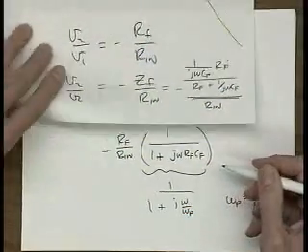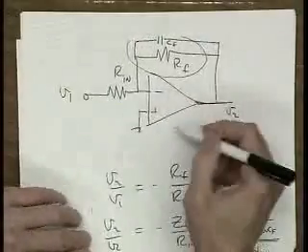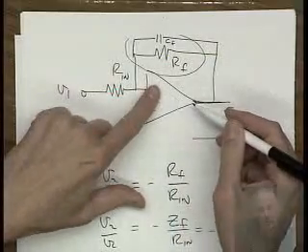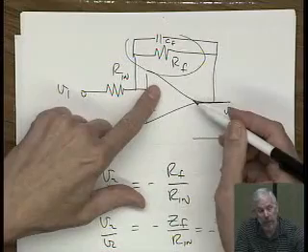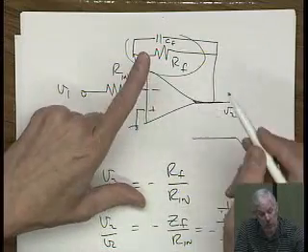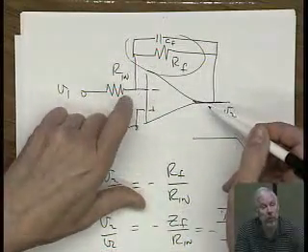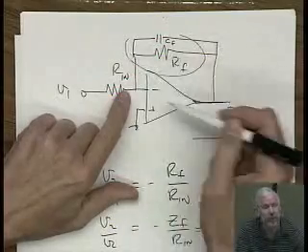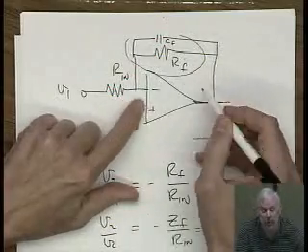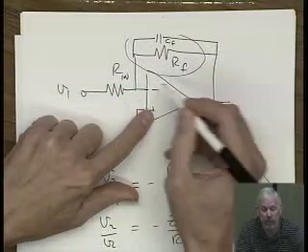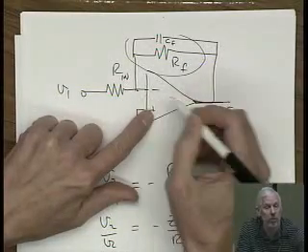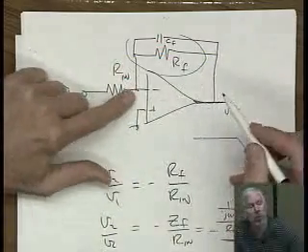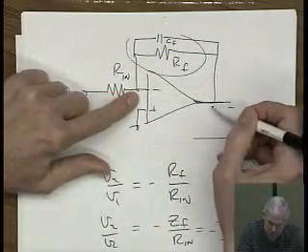So I can take this op amp that you're going to make nice and stable for me, okay? And notice what's going on here as we go up in frequency too. What's happening? We're getting more and more feedback, right? So we're going to have to make this circuit stable against the situation where we have feedback of 1 across here. We're just feedback all the way. So that's kind of why you often have to work by the worst case stability condition.